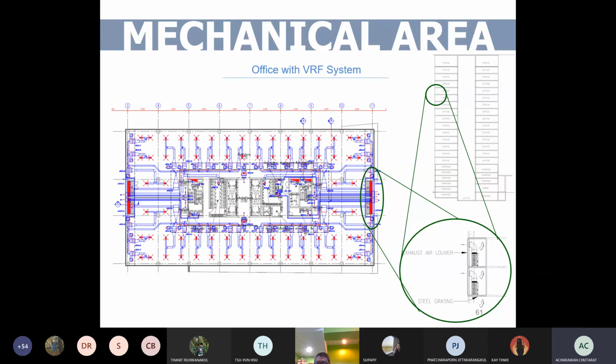Okay, thank you. So the students have to provide a kind of access door, maybe from the main area to the condensing unit. Why I recommend 4 meters: because the split type was tested in the factory and got the Mark 5 from EGAT. When they design for the best efficiency, they design at 4 meters.